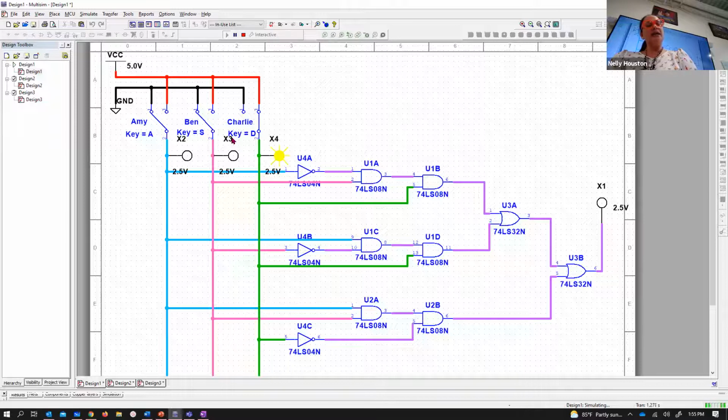So I test by saying, okay, I count in binary, right? 0, 0, 0, 0, 0, 1, 0, 1, 0, 0, 1, 1. And I know that's supposed to turn on there, right? And then at 4, 5, 6, and 7 should be off. Do you see how to go about testing it? And then you press stop by pressing the red square, and you know that your circuit's working. Okay, testing it is pretty easy once you build the circuit. Again, you just press run, then toggle the switches and press stop. Okay, let's start by building the switches.